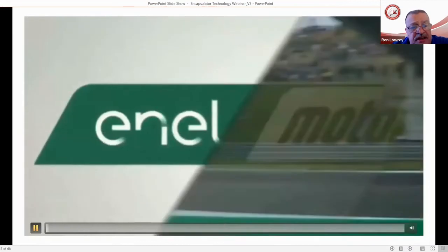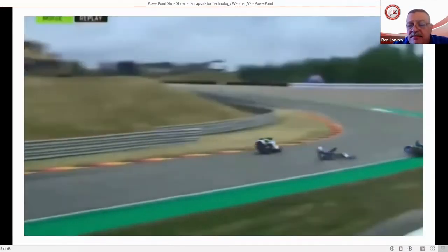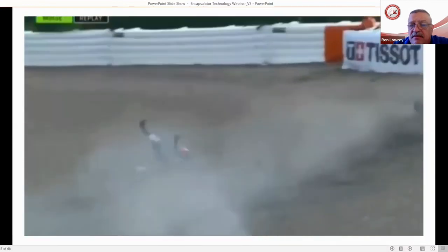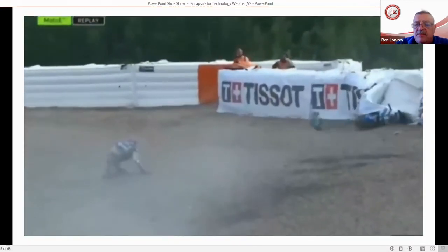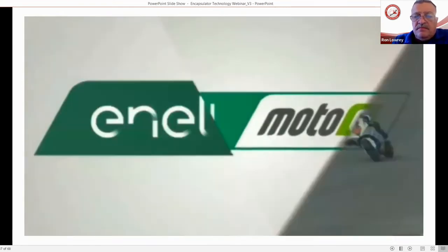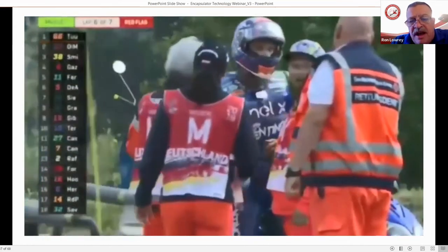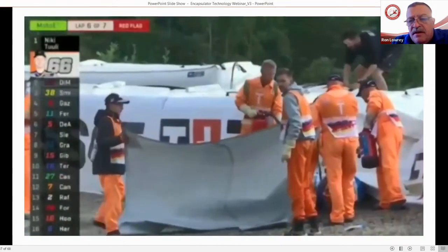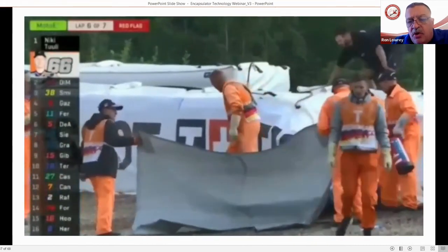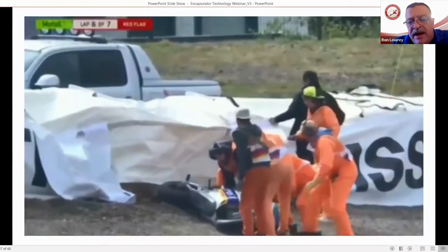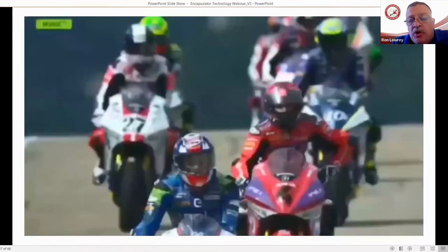The video here is a wreck on the racetrack. And again, you see the response crew out there with the F500 extinguishers actually controlling that fire, cooling that battery, and not even fire. They're mainly cooling the battery, stopping that thermal runaway. So they're cooling the battery before it even gets to thermal runaway, just to ensure that they didn't have a fire that they had to deal with.